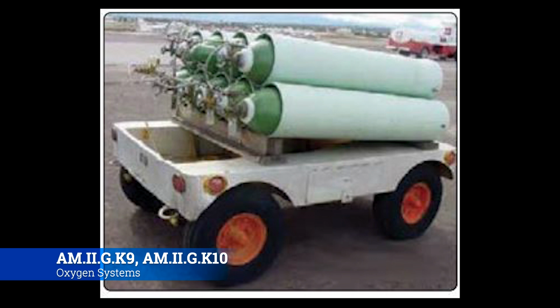Anyways, then you're going to connect the cart from the hose and begin to fill it. You're going to watch the pressure go up, but you're also going to watch the pressure on the bottle itself, and make sure that it doesn't drop too low. Whenever the cylinders are equalized and they're where you need the aircraft to be, then you're simply going to do everything in reverse. Make sure that you put the bottle back the way you found it. Make sure that it's super safe and taken care of, so you can use it again next time. Always do future you favors, so you're set up for success next go around.